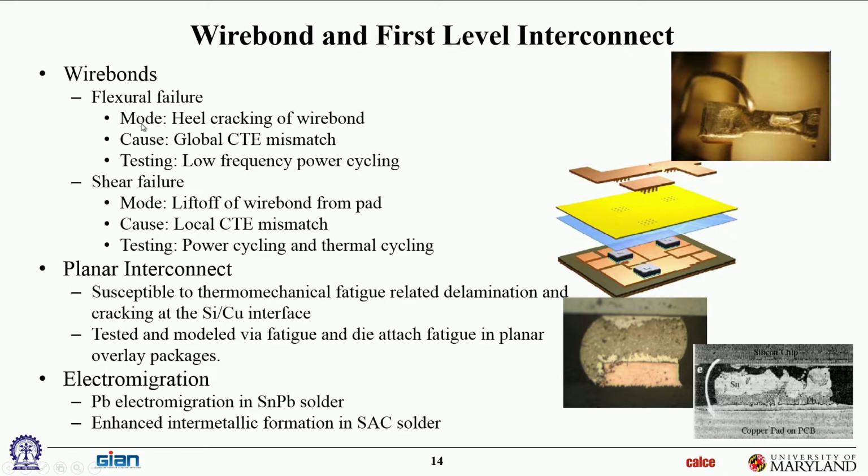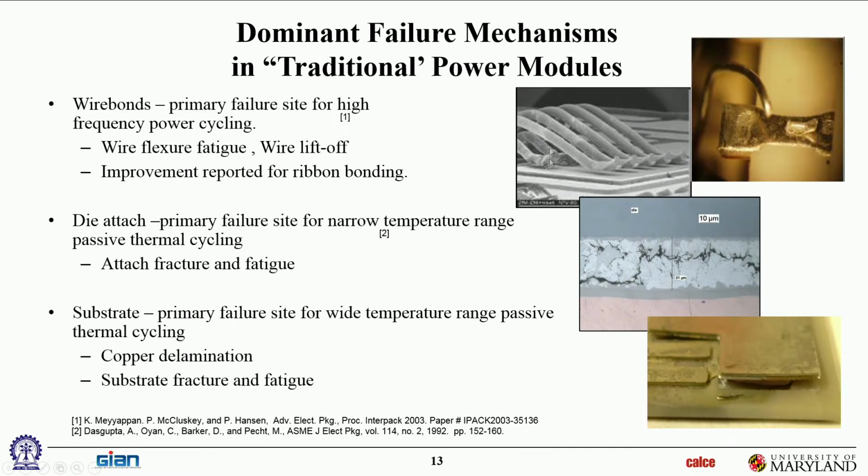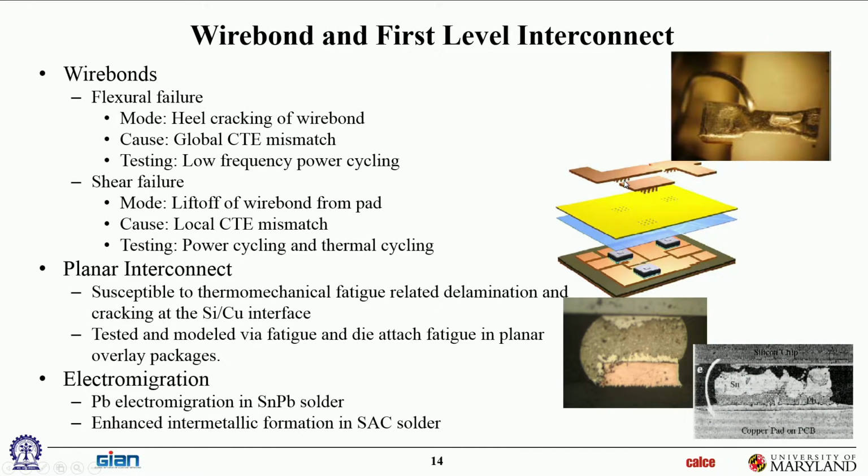This is just a repeat of what I said in the last slide, so let's skip over that portion. Let's briefly talk about the new information here, that planar interconnect. There are architectures when you have to get to real low profile packaging, where you don't use big wire bonds, because these are big wire bonds. So the height is pretty significant in terms of electronics assembly. When you want really low clearance packages, both for electrical and geometric reasons, then people go to planar pack.